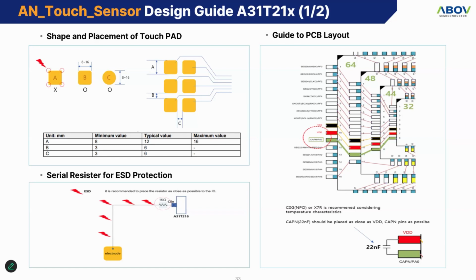This cap is essential for sensing touch IC charging and discharging. You should select the best cap on the market that has the minimal offset in change caused by external temperature. And also, you should consider adding a 1000 ohm resistor to the pin for ESD protection.